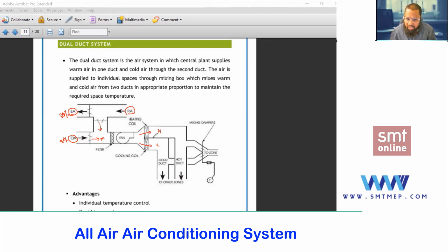And this duct is not connected. If it is connected, it is with insulation, or I'll consider a separate duct with some distance. So here hot air in this duct, cool air in this duct, this branch for cool air, this branch for hot air. You see this branch is running backside of this hot air duct. It's not mixing here.